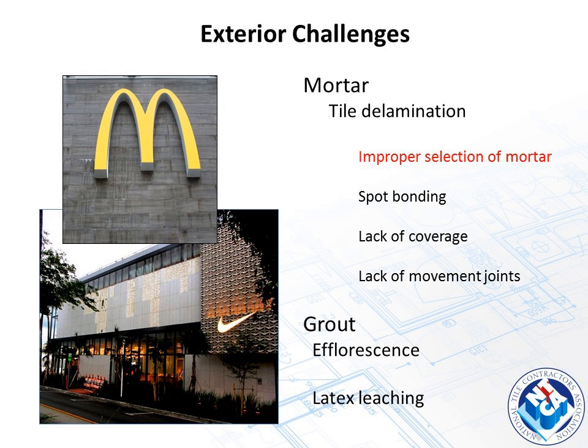The bottom, unfortunately, it's a store in the Miami area, and the general contractor called me and said that they were losing tiles. The mortar wasn't bonding. So he sent me some pictures. It's probably 4:30 at night, 5 o'clock when I'm trying to get out of the office. Last minute I'm downloading some pictures from the job site. When I looked at the pictures, I noticed that they're all spot bonded, and these tiles were roughly 2 foot by a little over 3 feet.